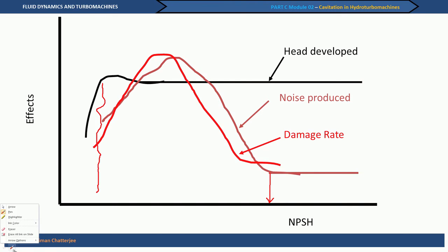This region is what the pump manufacturer would also like to avoid, and hence the manufacturer will say that there is a 3% head drop. I told you that this is the 3% head drop that the pump manufacturer will talk about, and this is what will be considered critical for a pump user. However, please do not miss the point that cavitation has already set in along this point. So, between this point and the cavitation breakdown, even with cavitation the pump performance is not affected, and hence as a user of the pump we need not bother.